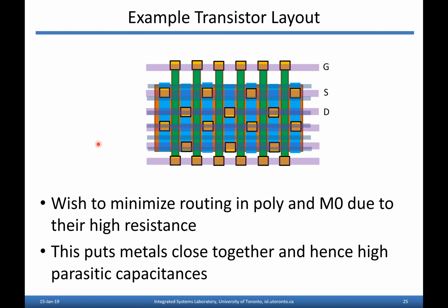So that's a typical style for planar technology. In a FinFET, it might look something more like this, right? You've got the fins running horizontally here. There are some similarities: the gates are the green lines running vertically, and their pitch is fixed. You cannot make them closer or further apart. If you're going to make a minimum gate length, it's got to stay on that predefined pitch. And the pitch is so tight at this point that you can't exactly contact the M0 layer with neighboring contacts.